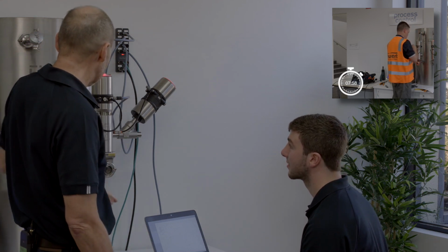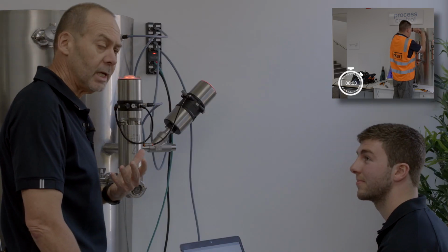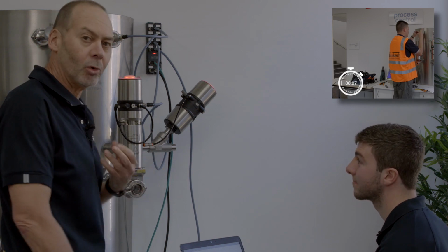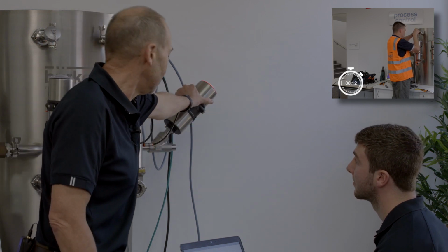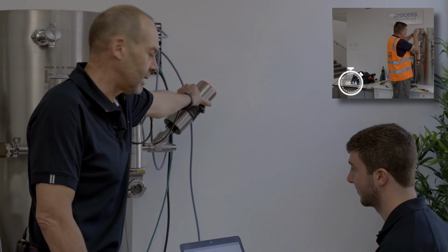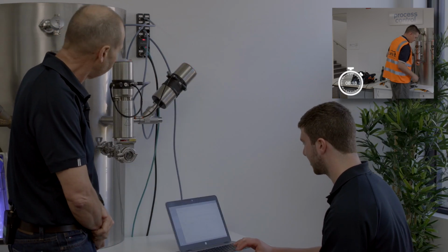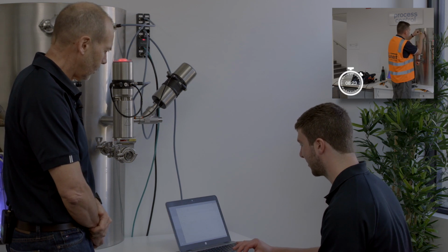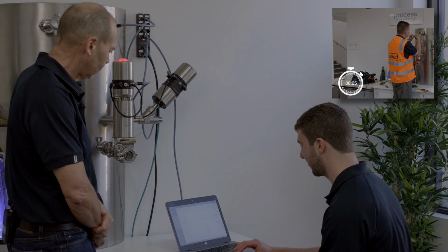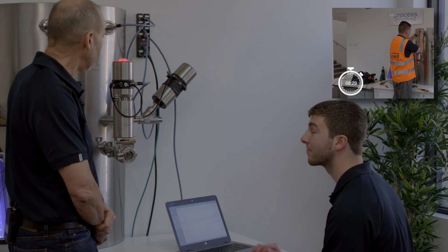So we've actually successfully commissioned everything. Yes. One of the beauties about digital technology is that we don't just get feedbacks and things like that, but we actually get more diagnostic data, etc. Can you actually tell me how many cycles this valve has done in its entire life? Yep, no worries. So that's easy as well with these digitally connected valves. So jumping into our diagnostics for the valve head, we can actually see that the valve has done a total of 1,845 cycles. So 1,845 cycles.